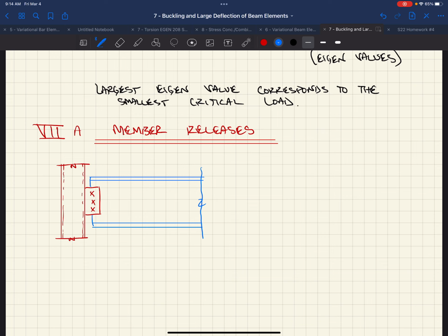Okay. Well, there are dimensional requirements in the steel manual that mean you can't over design the shear tab. It's gotta be a certain thickness based on the welds and things like that, so that there's actual rotational ability for this connection. They wanna make sure that it doesn't act more than just a pin, right? Even though it's gonna act more than just a pin, we idealize it as that.